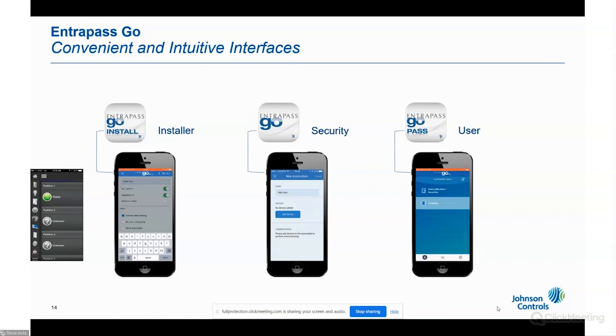This is a diagram showing how the connectivity is for the iOSmart readers. So as you see, you have up to 500 feet per line on RS485. You can connect the in readers, out readers, your T-Rex and your door contact right into the reader itself for wiring cost efficiency. It's a lot more convenient if you can wire these devices at the reader instead of going all the way back to the panel.